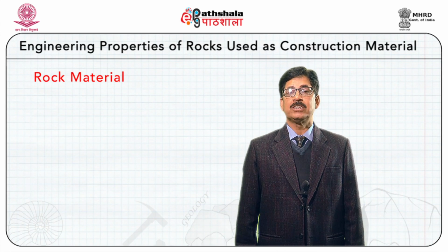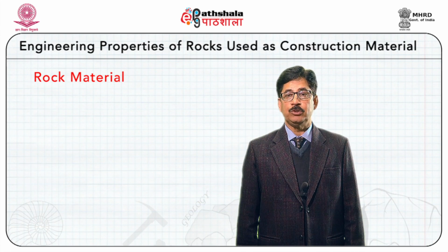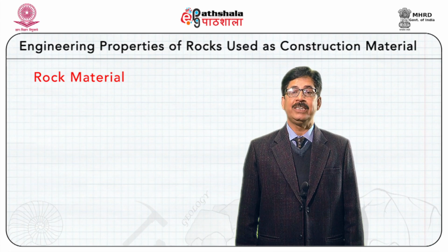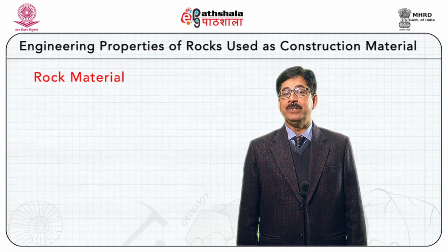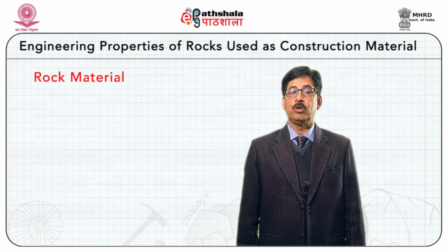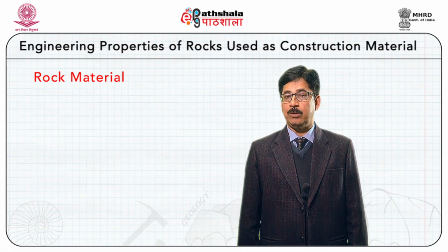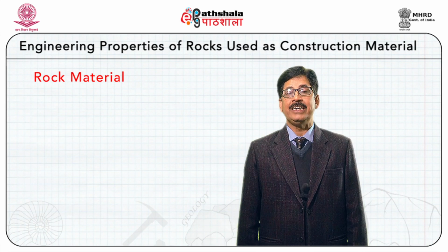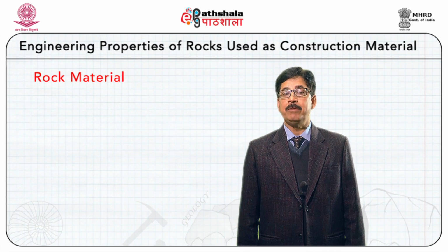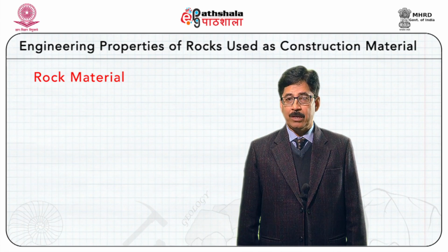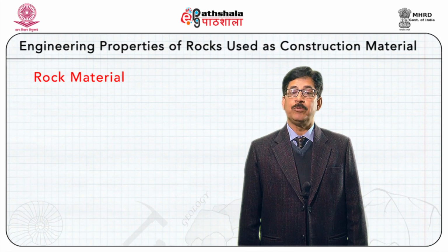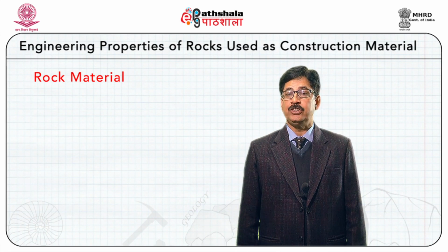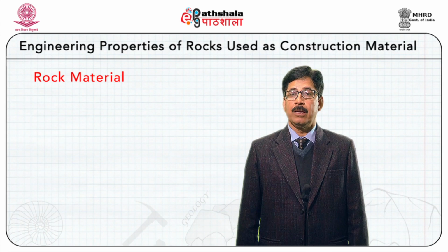The strength of rocks comes from its texture and mineral composition, and weakness creeps in due to alteration caused by weathering and deformation. Rocks which are taken from near the earth's surface may be somewhat weak because they have been affected by weathering, and the rocks which are taken from deeper parts may be fresh and strong. Because rocks are not engineered materials, their properties can show extreme variation from place to place.